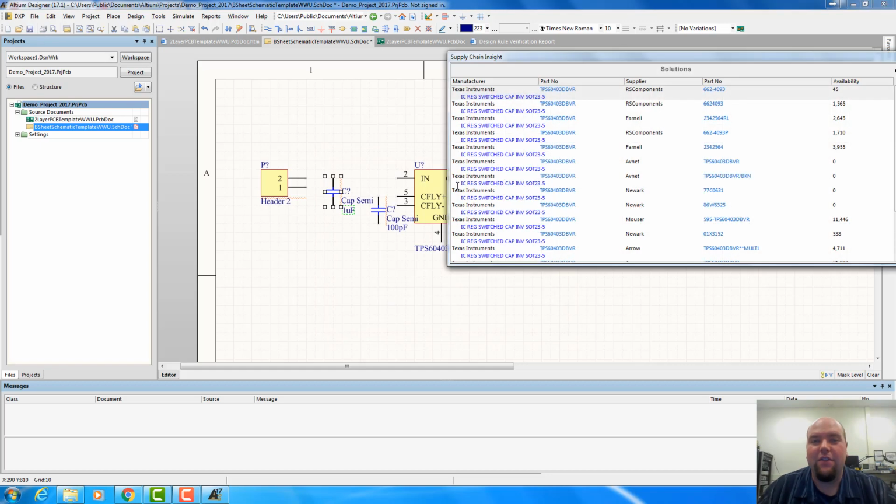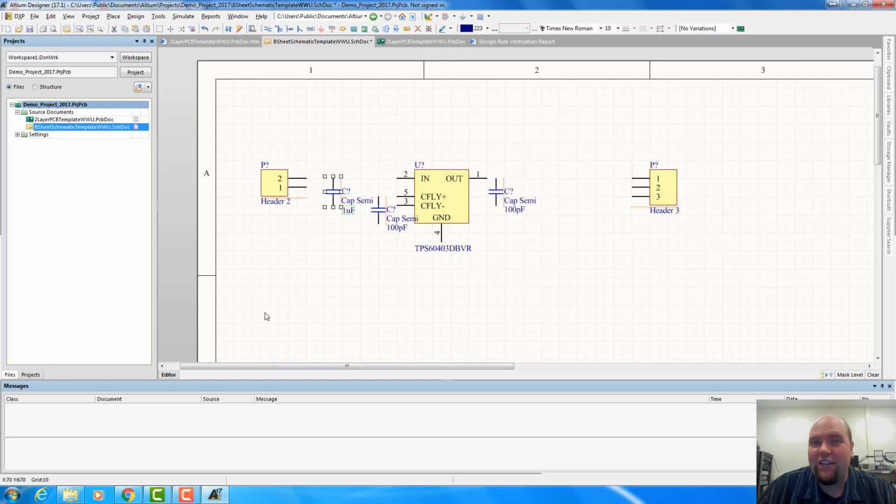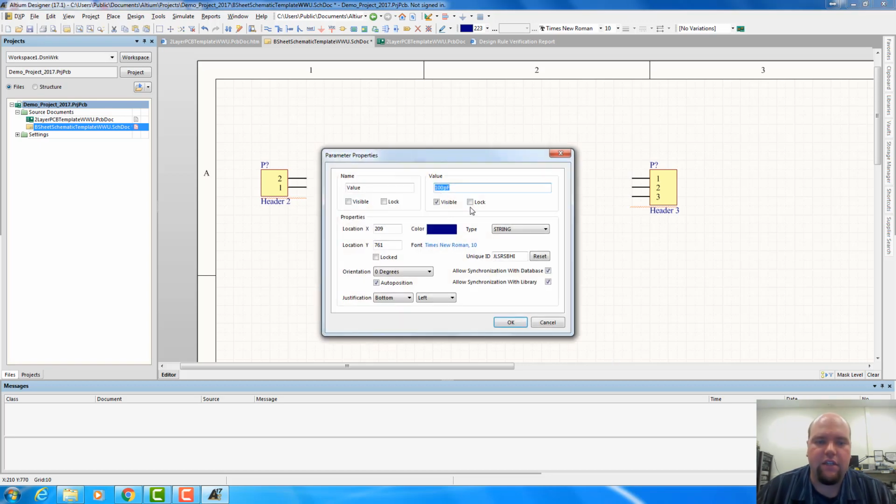It's important to keep in mind, though, that the only thing we've done is change that text. By specifying a different capacitance value, we haven't changed anything physically about the system. So if we typed in 100 microfarads there, it wouldn't give us nearly a big enough footprint for a 100 microfarad capacitor. The only thing is, it's telling us when we do a parts list or a bill of materials that that component needs to be a 1 microfarad component. But we'd better make sure that we have that in the footprint that we had for the original part. So I'll do that for all the rest of these too.